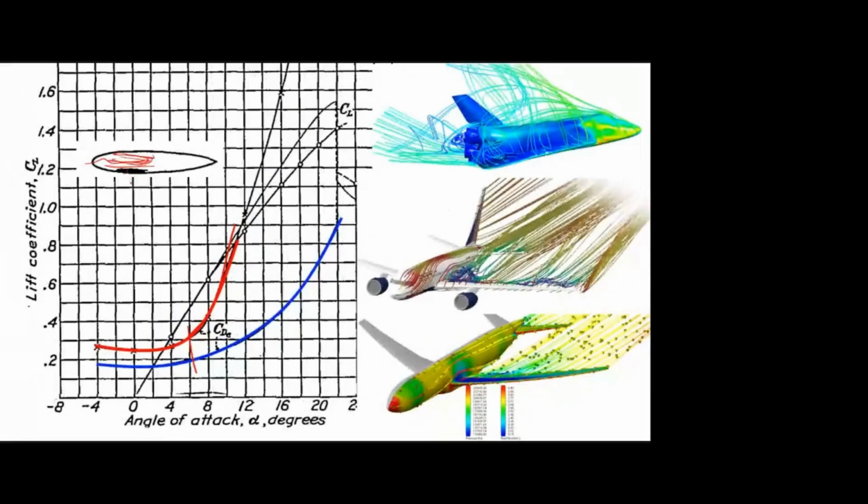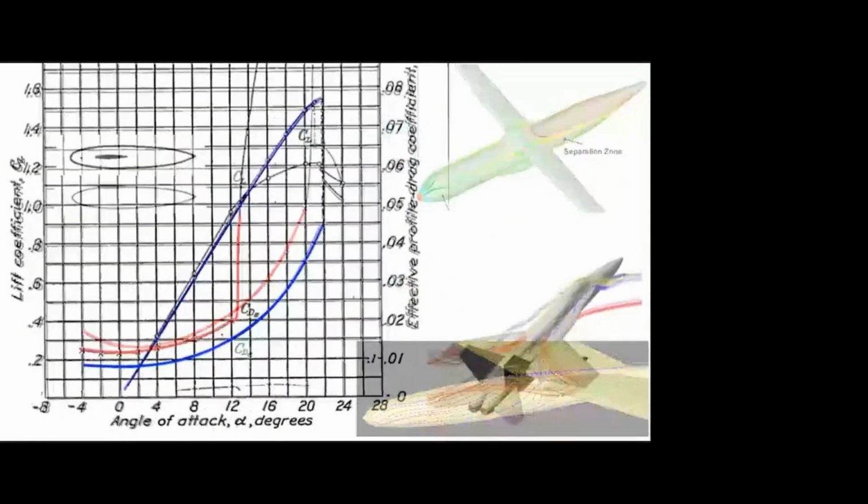Okay, so it is easy to attach it. All those parts can pass through the lower surface, so the fuselage is not affected. So for manufacturing and other structural considerations, we are going for low wing, but this produces high drag compared to the mid wing and high wing. Is that clear?